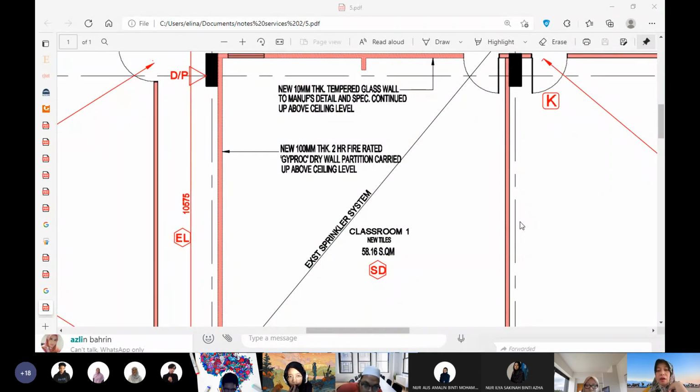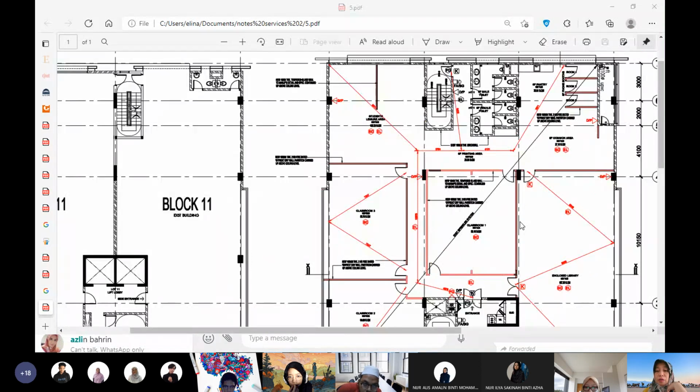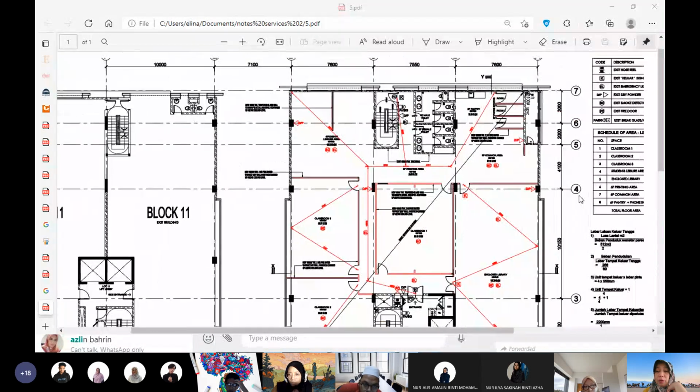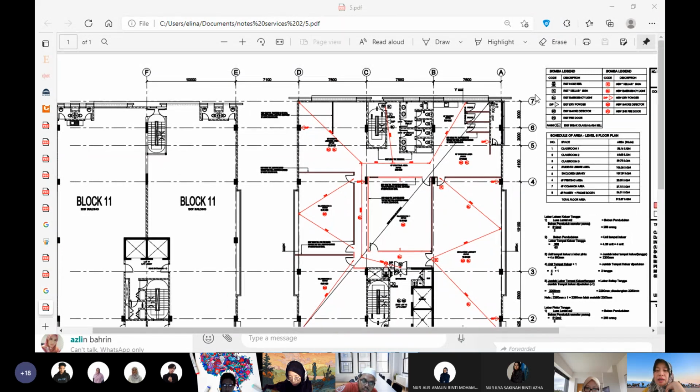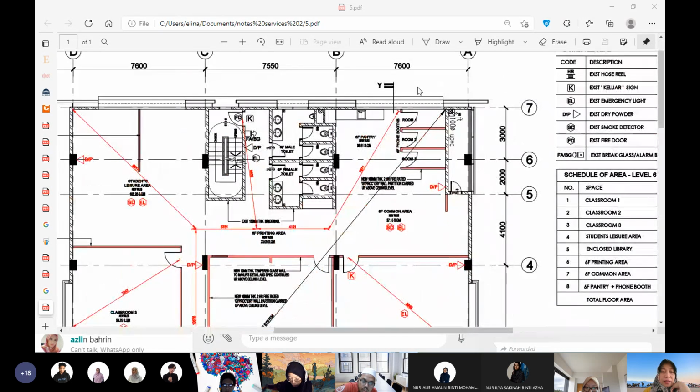the building is on the sprinkler system because of the height and the volume, because they need sprinklers. And also you may see the distance, the perimeter from one door to fire. This is how they calculate the perimeter. They calculate based on perimeter. See, you cannot simply cross like this. What is the distance from room 1 to the fire staircase? You cannot simply do it like this. You cannot draw like this.